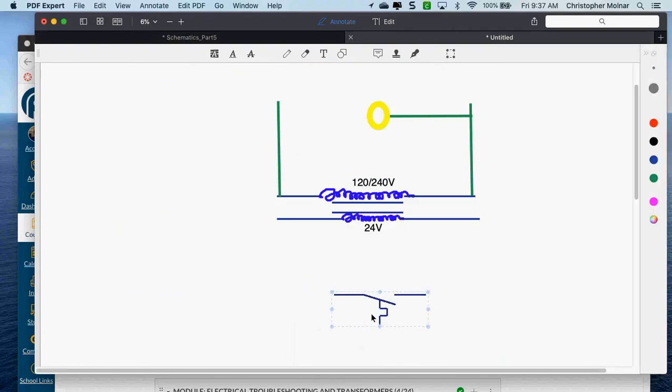So this is on a wall in some kid's room. I don't necessarily want my 240 volts on the wall. It's dangerous. That's why I use 24 volts. So what do I use to control this line voltage load, this heavy load, with my thermostat down in the space?